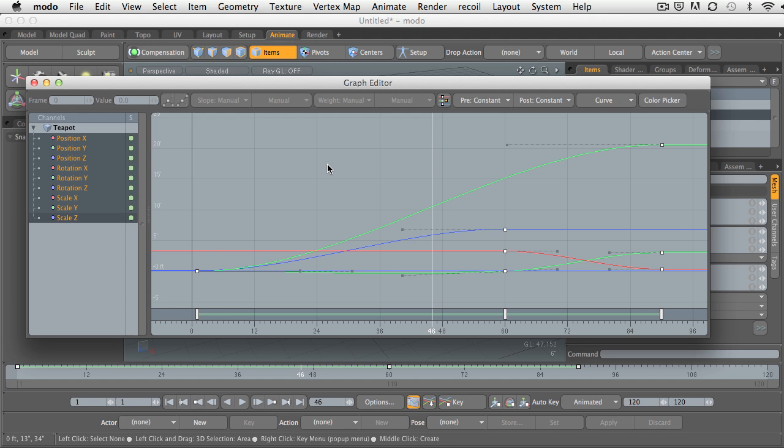Okay, so this is one way that we could very quickly go in and adjust the location of our keyframes. The little white cubes inside the graph editor represent the current location of our keyframes. Keep in mind that left to right on the graph is time. So if I wanted to move all of these guys back, simply left-clicking and dragging back to the left here will move its position. Also, we can grab these little widgets down here at the bottom.